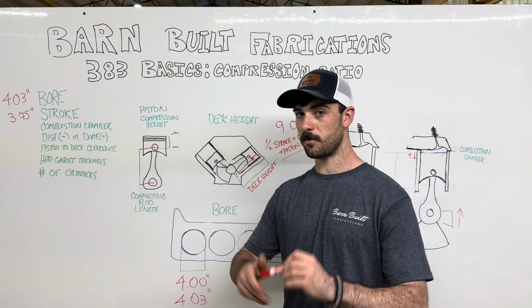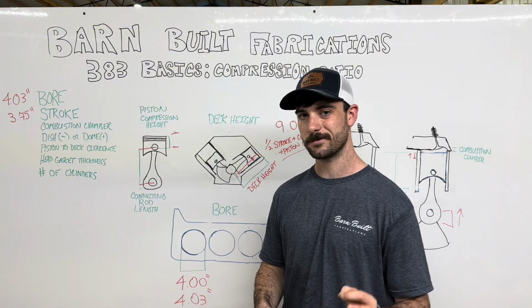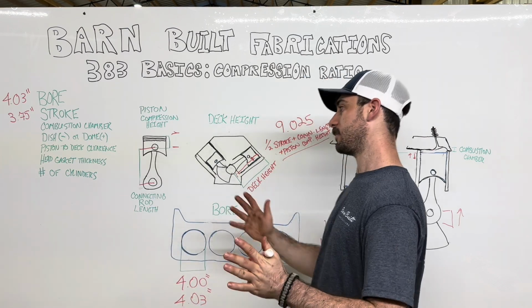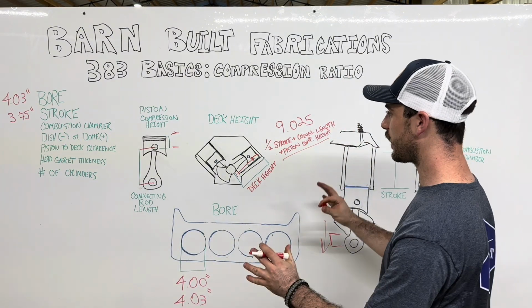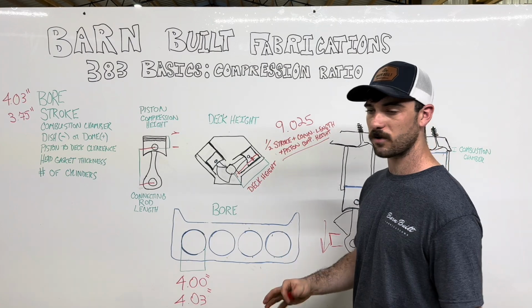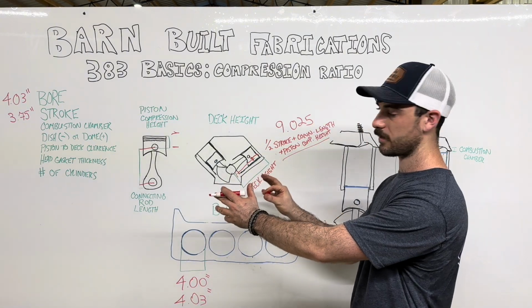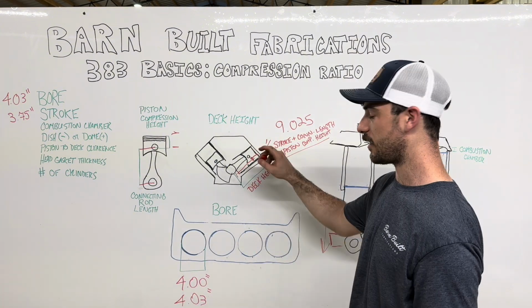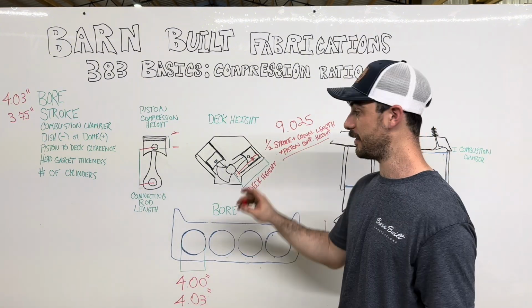So I don't want to go too far on that. I probably already went a little over into getting a little bit confusing. But the meat and potatoes of all that is, if you have everything in front of you, if you have your short block and your rotating assembly installed, use a bridge, use a dial caliper, and you're good. Okay, that's how you get that.